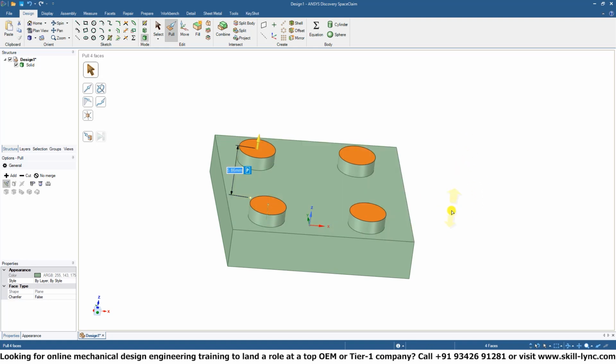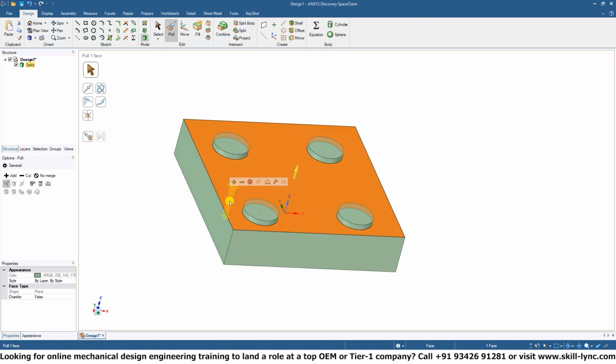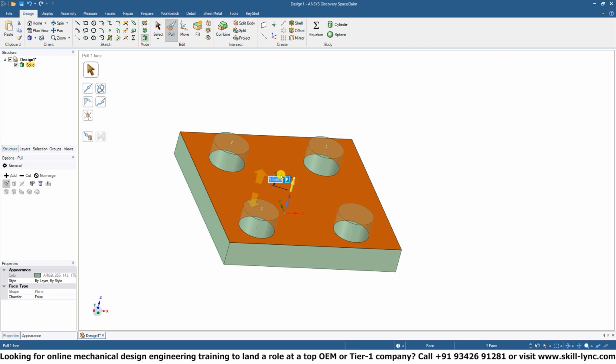Similarly, as we covered in the previous week, if you wanted to give some specific dimensions to your pull or extrude, you can do this right next to the parameter window box. So if you wanted to give it an exact dimension of 5 millimeters, you can do so. Also, if you wanted to affect this one as well, you could do that too.